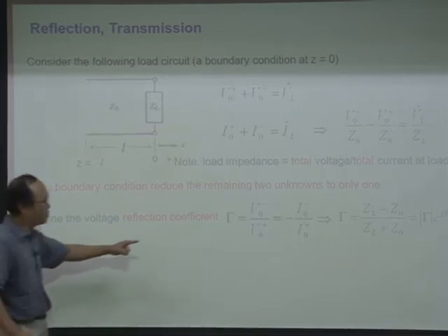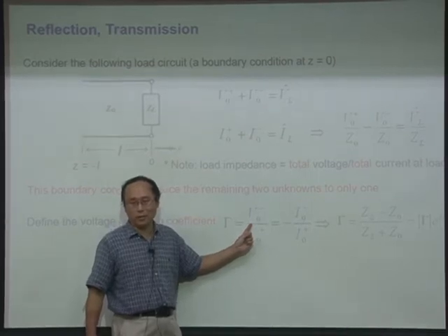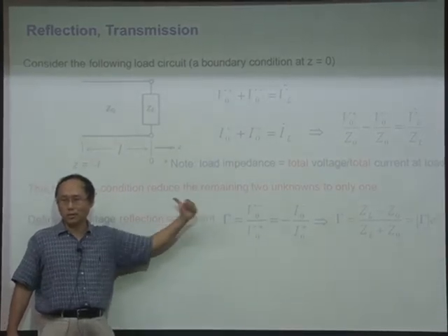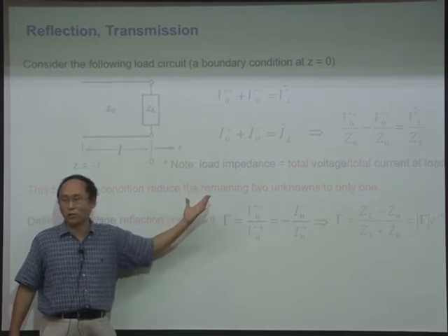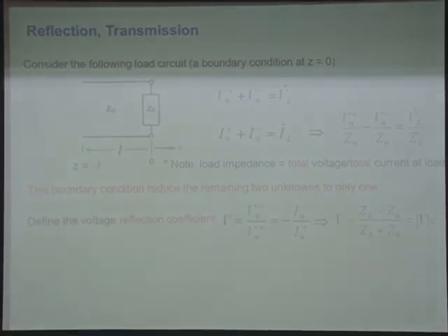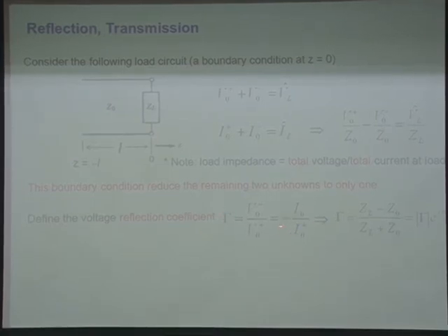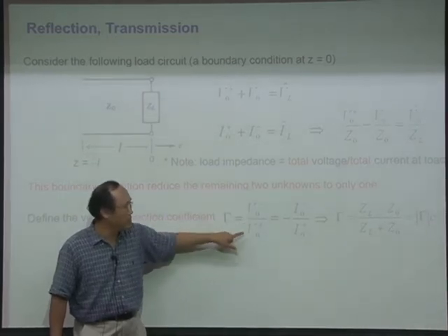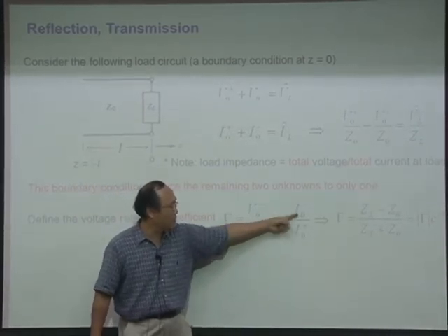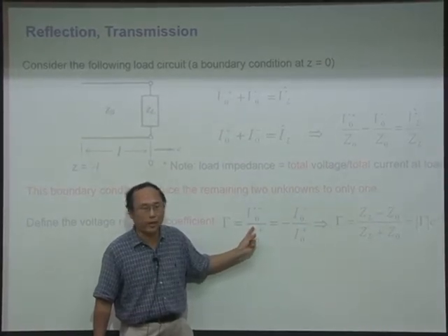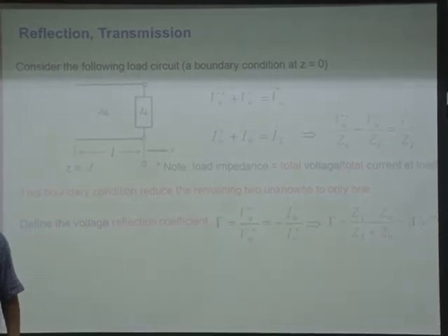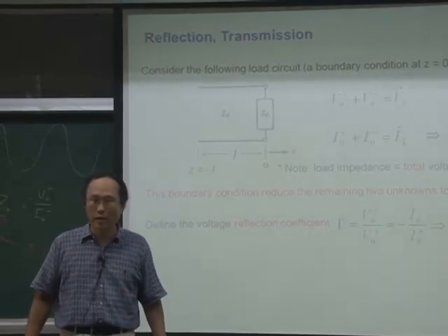This tells you, for example, if you come up with 1%, it means that 1% of the voltage is reflected back. It could be 3% or 20% or 100%. But for the ratio in terms of current, you have to add a minus sign here. And be careful that this is not the energy ratio; it is the voltage ratio. So it could be a negative value. For the energy, you take the square. As we introduced above, for any wave, the square of its amplitude is proportional to the energy.